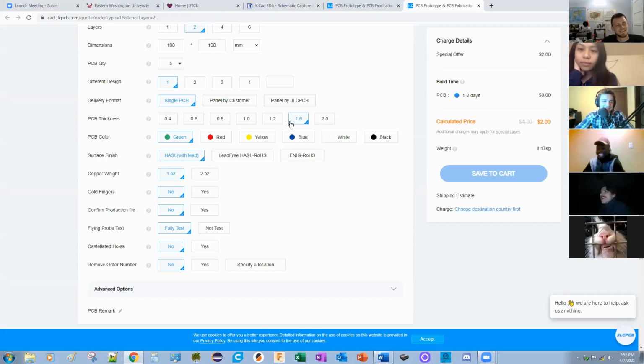So as far as options, you can select a thickness. I think 1.6 is pretty standard. That's the thickness of the fiberglass that the board's made out of. You can also choose a copper weight. We made a motor driver PCB and used 2-ounce copper, if I'm not mistaken. Yeah, that's right, because of conductivity. It was higher power, so the 1 ounce copper wouldn't handle the power; it would have melted the traces. You can either get wider traces or thicker copper, but you can only make a trace so wide, so at some point you need a higher copper weight.